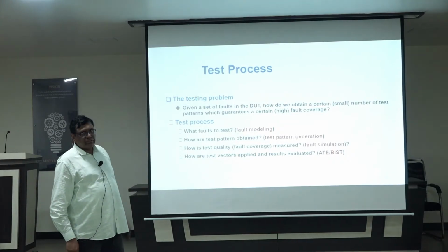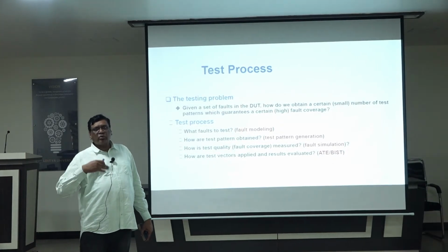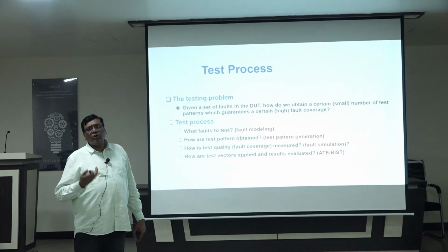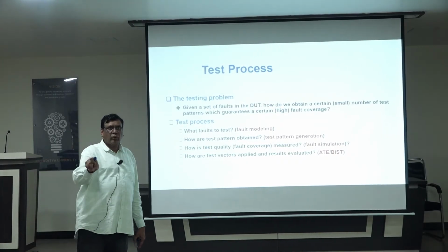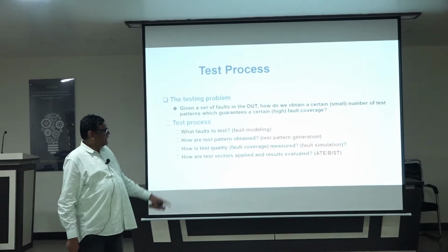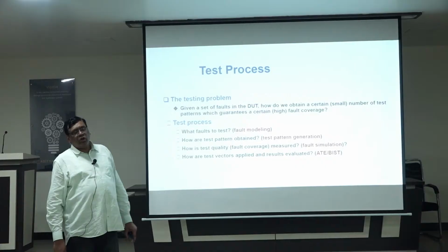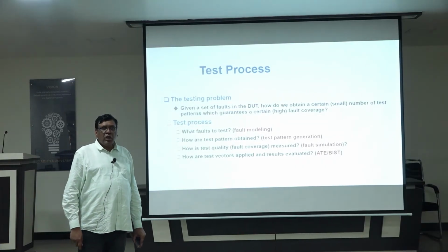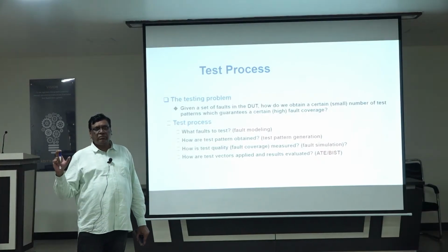Test pattern generation: you have to generate the pattern. Generating the pattern means you have to create some signal on the input to trigger a 0 or a 1 on that node. Okay, that is the next step. The third step is fault simulation. How many nodes are there in the IC? How many nodes are tested?